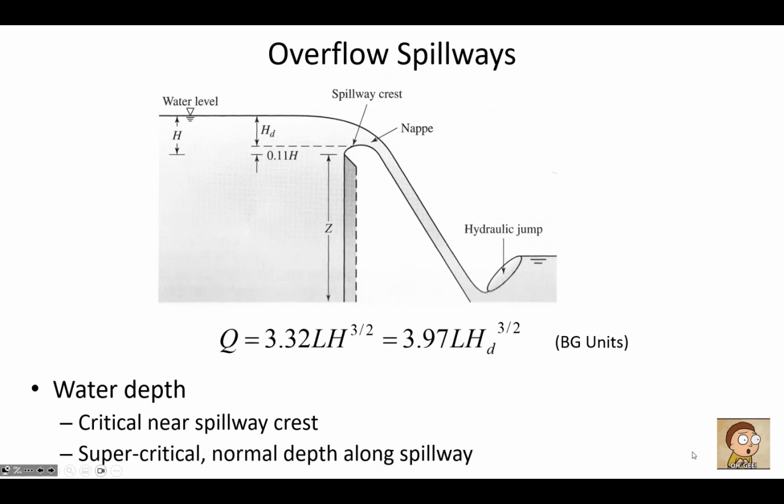If it has some forward velocity and then it's falling as it goes over a sharp-crested weir, then the water that's tumbling down the face of the spillway would follow this shape. And so if you want to accommodate the highest flow rate possible, a big flow rate Q, then you'd follow this OG shape, and it would minimize the variation in the water height.